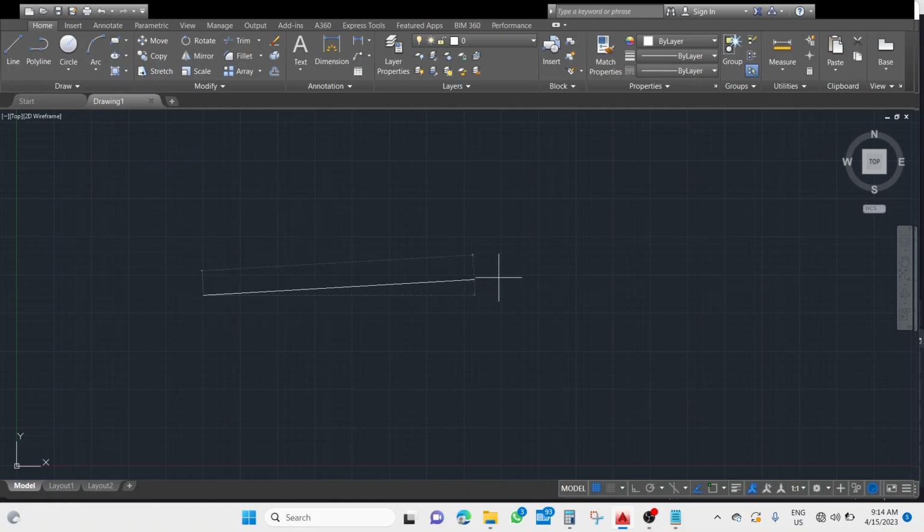So let's see here, I am moving the cursor to my right hand side to draw the line in horizontal direction. Now let's see here, this line can be rotated in any direction. Okay, but let's see, I want to draw only the horizontal and exactly vertical lines. So to draw the horizontal and exactly vertical lines, I have to activate the ortho mode of AutoCAD. So ortho mode lies over here. You will find the two perpendicular lines. So it is ortho mode.